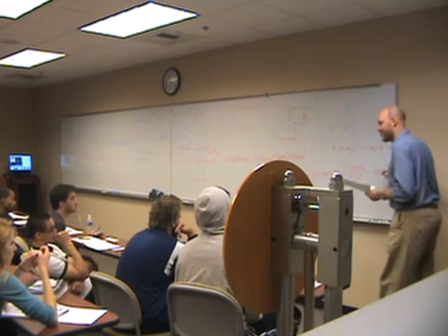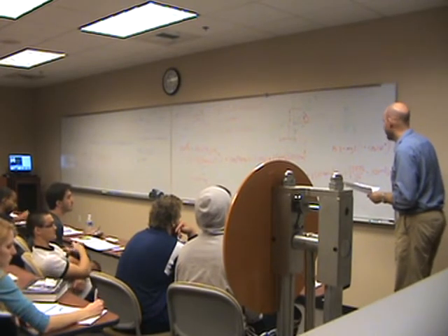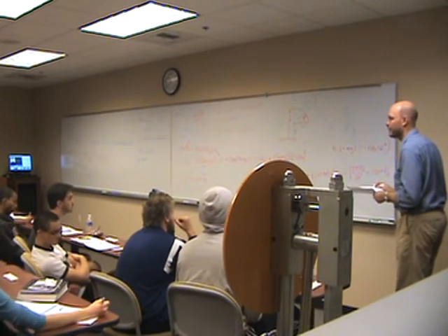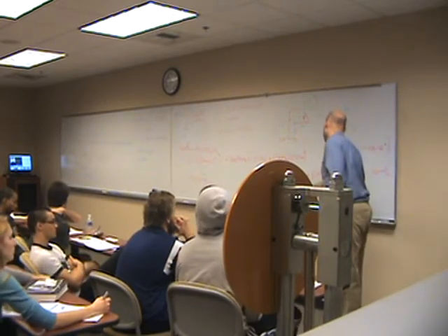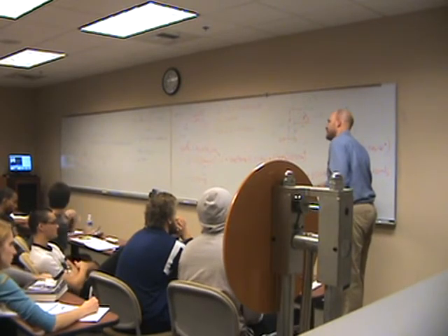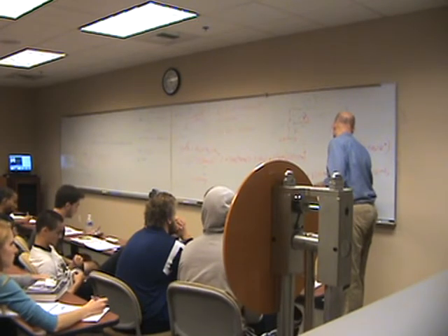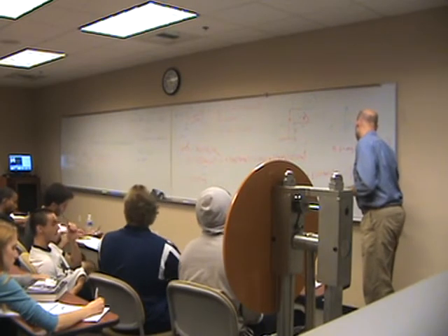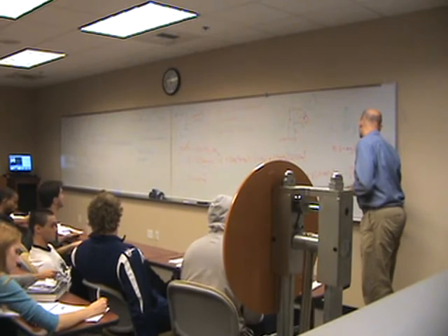So obviously this is a book problem because the answers turn out so nicely. Reality is never quite that easy. So how fast are we going? What is the speed? v equals r omega, which is equal to 0.4 meters times 10, and that's 4 meters per second.